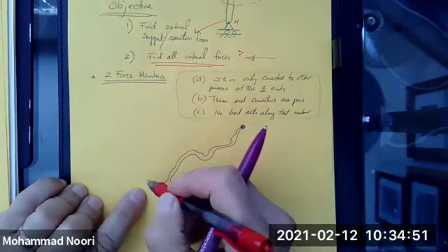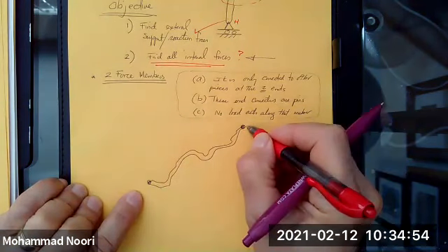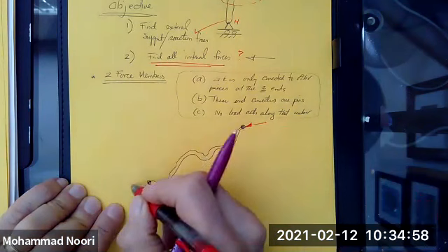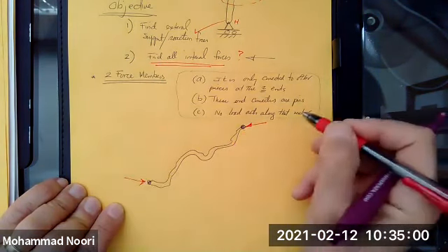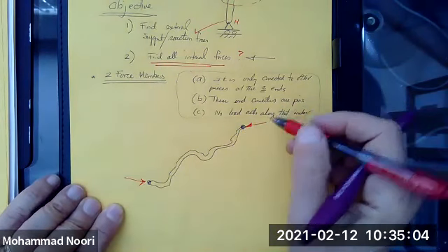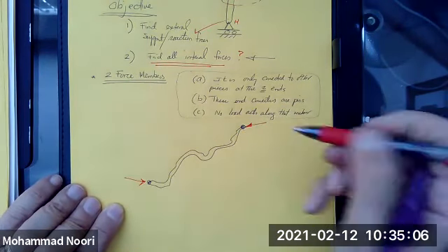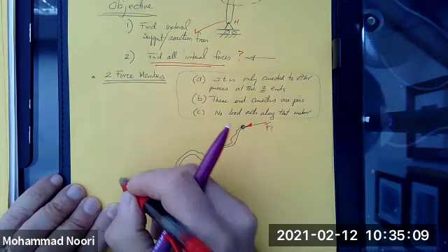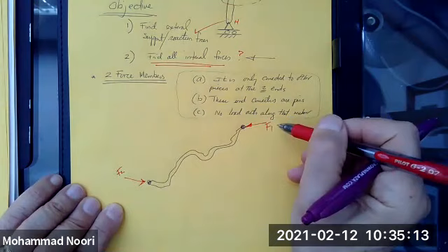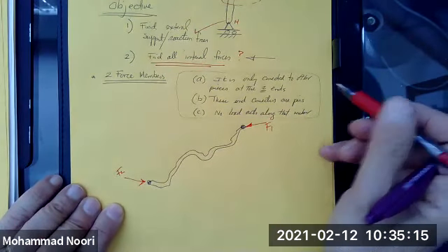So you have basically an unknown force here, an unknown force here, which you typically break down for the analysis into their two components, right? So let's call this F1 and F2. And you say for this member to be in equilibrium, those are the two forces, right?